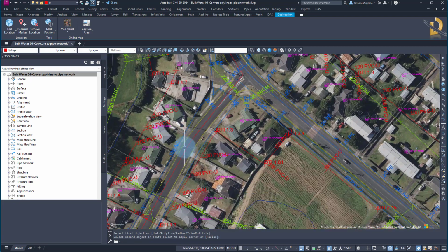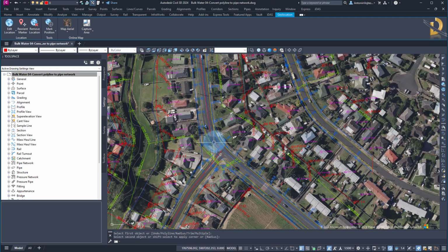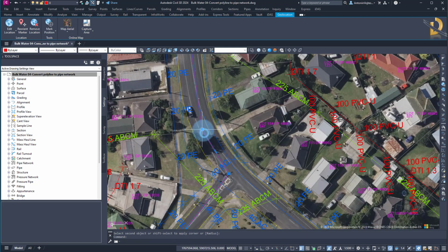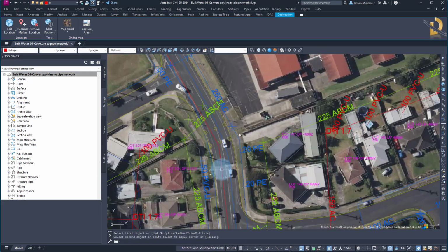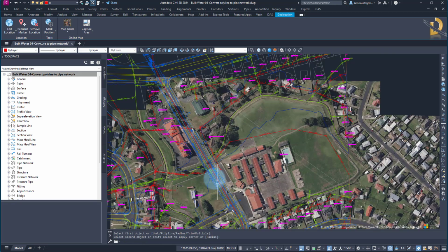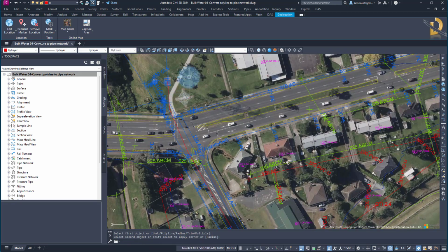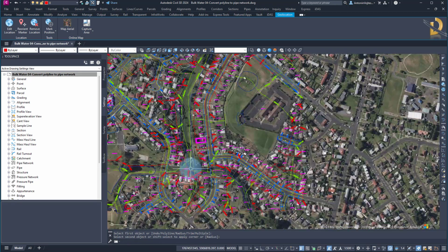50 meters. Then here I can leave it as it is, or if I want, I can introduce the same. The same applies here. I want to do it something like this, fillet, and again I will use something like 50 meters. The same applies here. I'll do it slightly like that, fillet radius, and then it goes all the way through and I'm happy with the rest. So I do have a polyline.